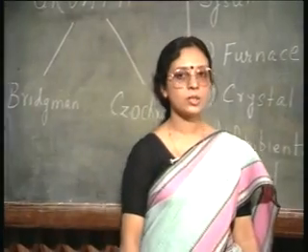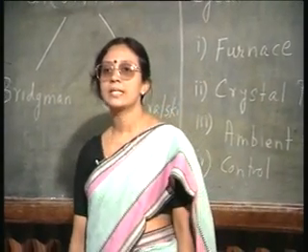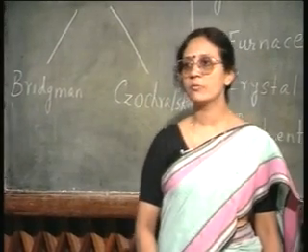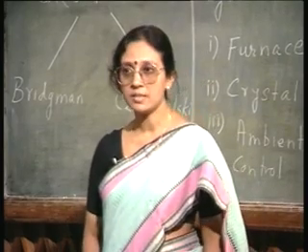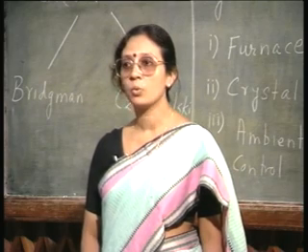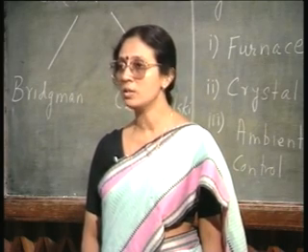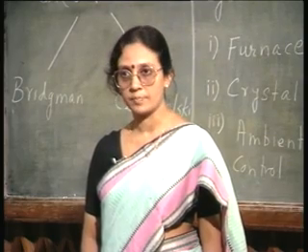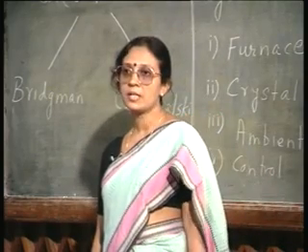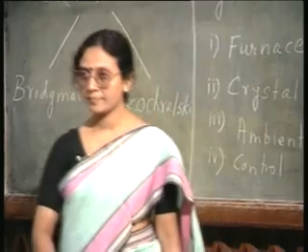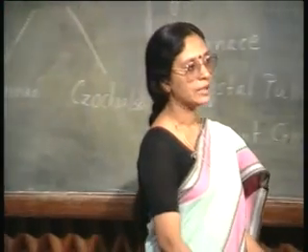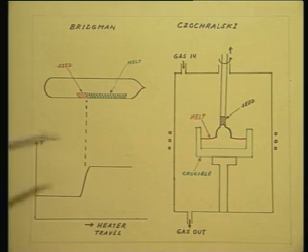And this quartz crucible is usually placed inside a graphite susceptor. A susceptor is, you can view it as an outer jacket, that is, I have a bigger cup of graphite in which I am going to place the quartz cup. The quartz cup is called the crucible, the graphite cup is called the susceptor. And the graphite susceptor is placed on a graphite heater, usually very high purity graphite heater, and the heating is usually done by RF.